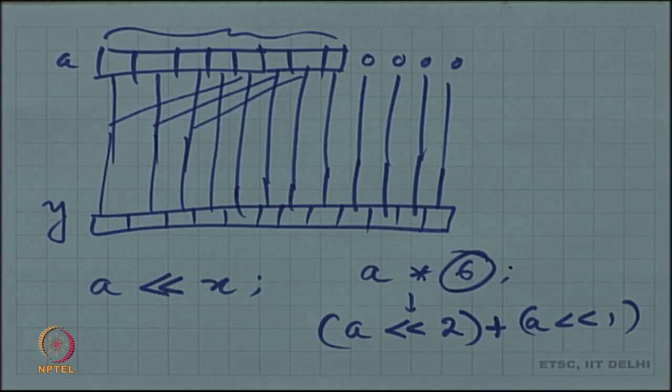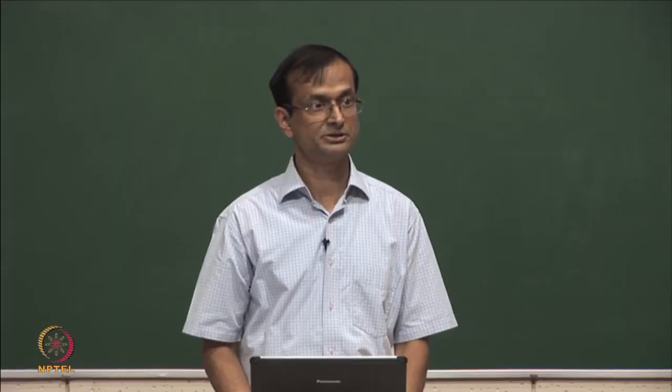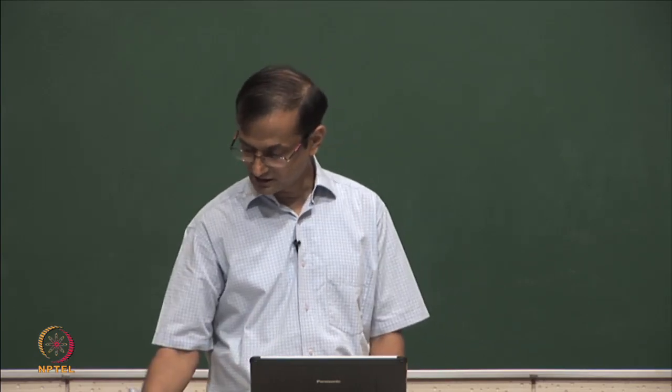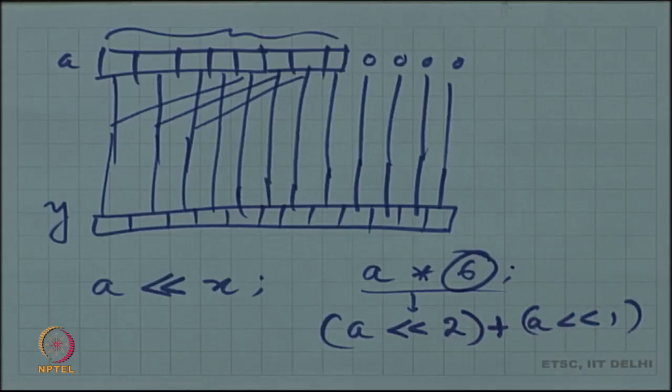The generalization of that is something like you have a set of variables, a set of constants. This happens in certain DSP kind of computations. You have constant coefficients with which you multiply variable data. So, several such multiplications are there. What is the best circuit to realize that set of multiplications, all of which are of this nature, a variable multiplied by a constant? The default one would be if you just had a multiplier for each one of them,